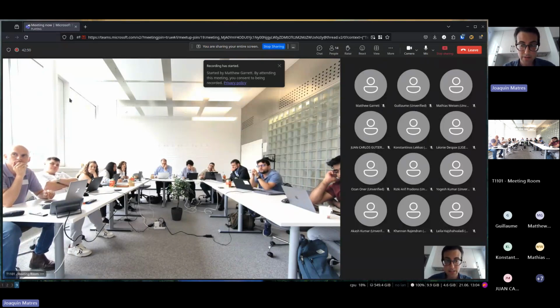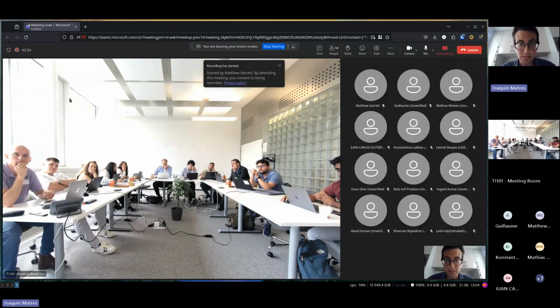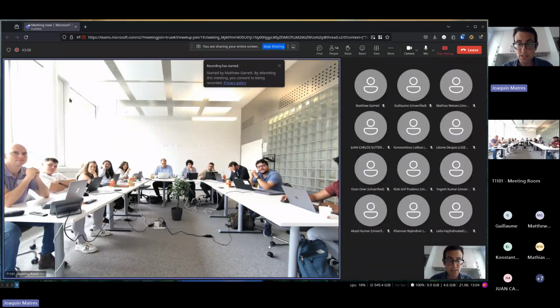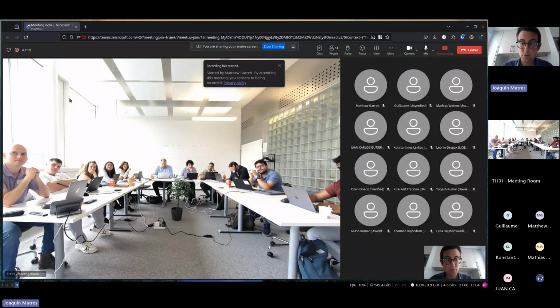If they don't have it, we may have done it in the Gdsfactory PDK, but if not, I can give you guidelines on how to do it. But it's a lot of work. Every foundry has many layers, and every layer has many rules. So it's actually better if the foundry is the one who builds the PDK and the DRC deck and maintains it.